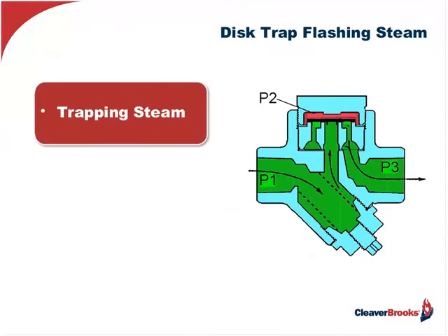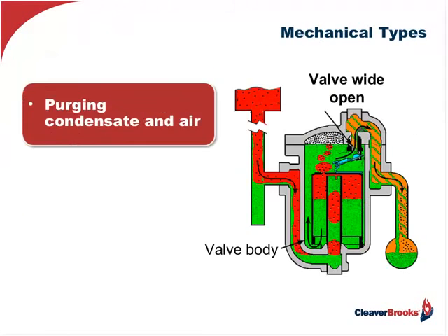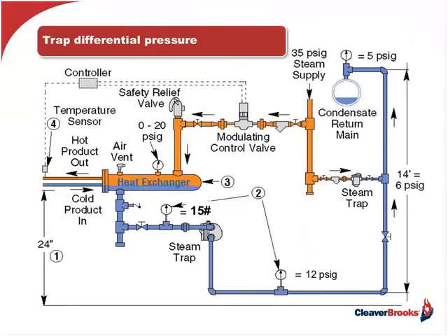So you can either resize the trap to meet the varying load conditions or install a power pump with the existing trap, and the power pump would then handle the varying load conditions, okay, where we don't have the proper differential across the trap, and where we do have the proper differential, then the trap itself would be evacuating the condensate. So it would be in tandem. We would have a power pump along with a steam trap to eliminate the problem of stall.